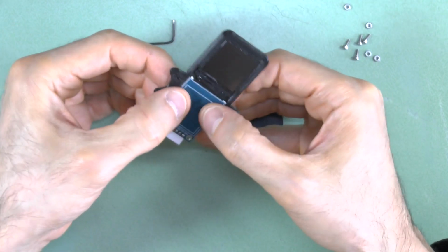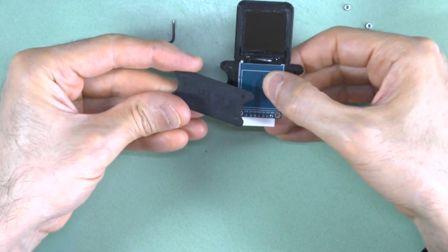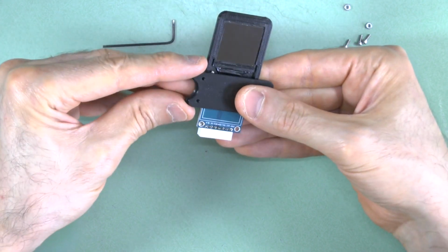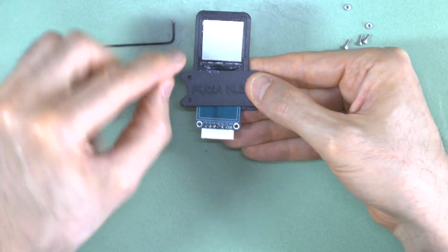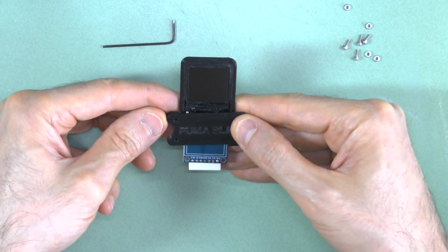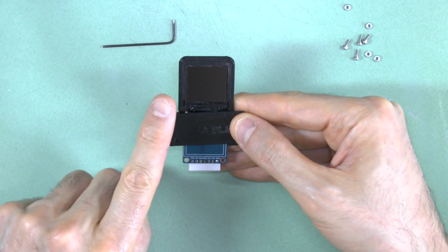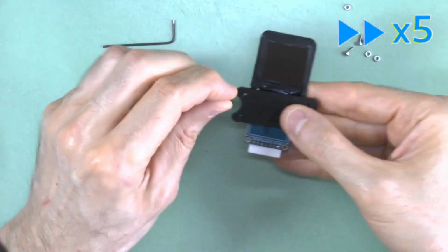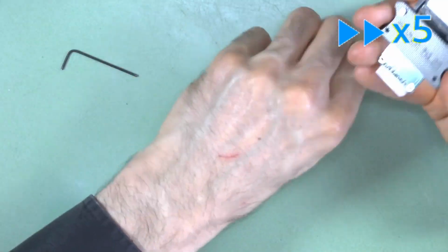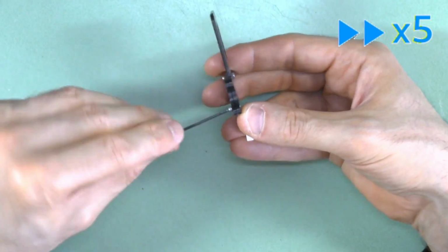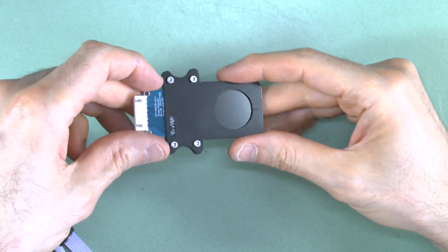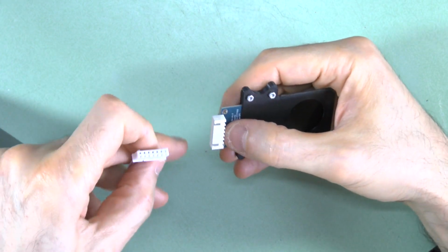Secure the handle cover on the IAD SLM with the 4 M2 screws and nuts as shown. Note that the handle and cover are not symmetrical. You must fit the cover as shown with the PUMA SLM label facing out and the letters the right way up if you hold the filter with the handle pointing down and the TFT screen aperture pointing up as shown. Test the resulting IAD SLM TFT to ensure it still works.